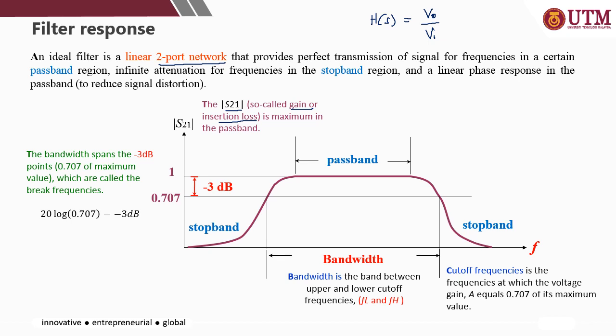Alright, so the value on the y-axis here is the linear value, and if it is in dB, it is 0 dB or negative 3 dB. Negative 3 dB is where the power has been reduced by at least 50%. And the bandwidth is measured across the 3 dB lines. So for example, here is f1 and here is f2. So the bandwidth is basically f2 minus f1.